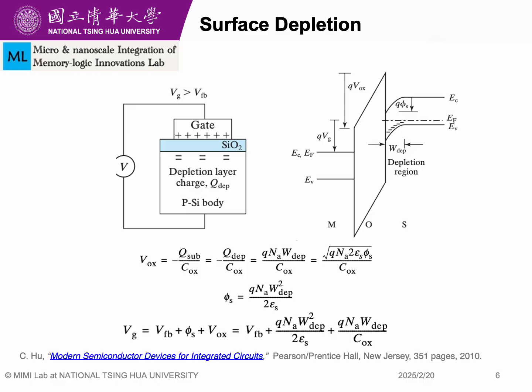As we know, the positive voltage will pull down the band. So the left hand side here will be pulled down. By what amount? It will be pulled down by the amount of voltage drop or the electric field across the oxide. Similarly, we will also see some surface potential across the silicon.